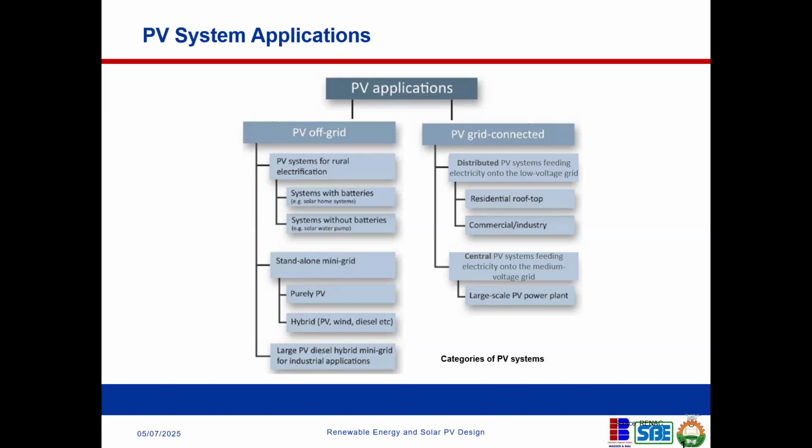But when you have it in combination with the grid, it is combining the electricity that is coming from the grid and that is coming from the solar system. However, it's going to prioritize the electricity that is coming from the solar system. The electricity from the solar system will be priority. It takes the higher priority of dispatch, right? So it will be dispatched first, and then the remaining will come from the grid. So when the sun goes down, the grid comes up, okay, and then your system can keep running. But again, what happens if there's a grid failure?